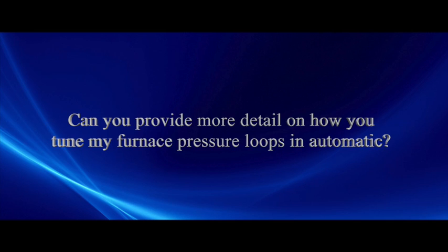And to show you how emotional an issue this is, people really got upset with that. They say, you don't want that. Some processes don't want any oscillation. Which processes are those? Again, the ones where there's no attenuating liquid volume, no well-mixed volumes downstream.